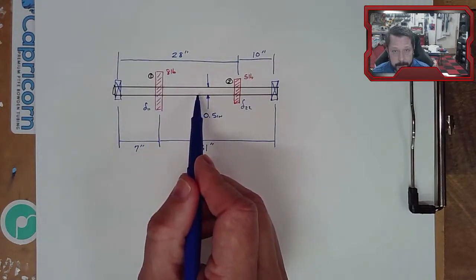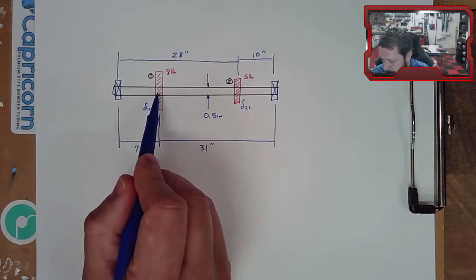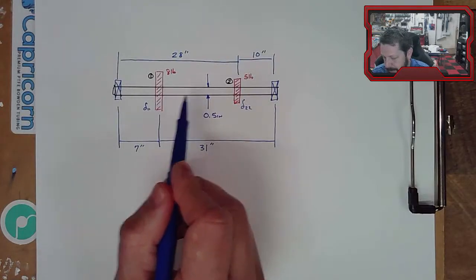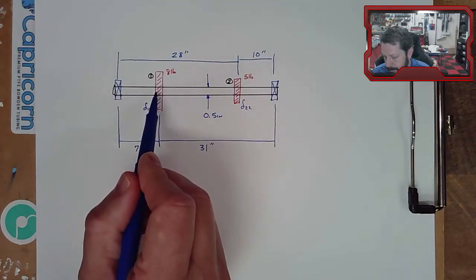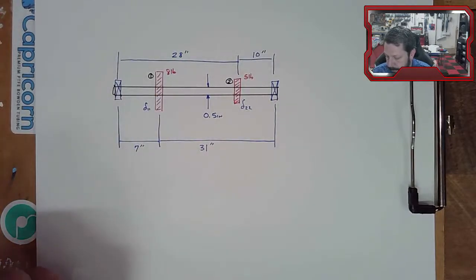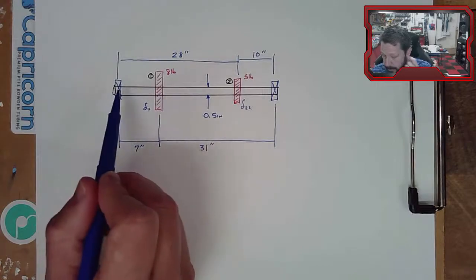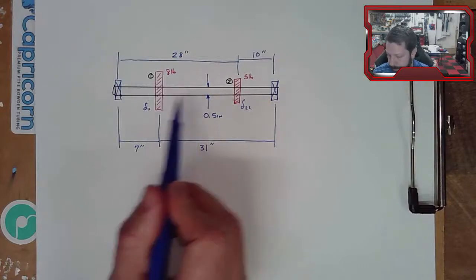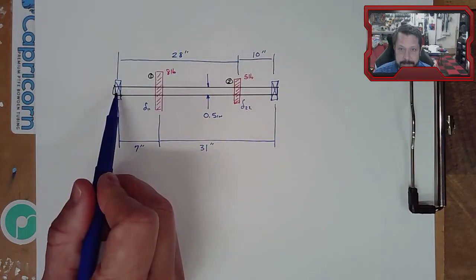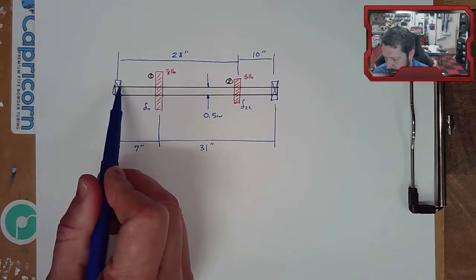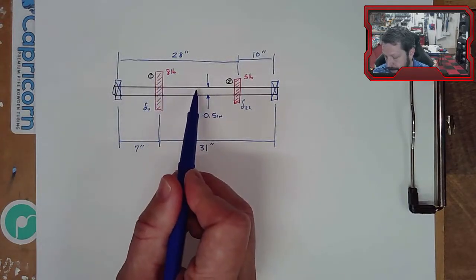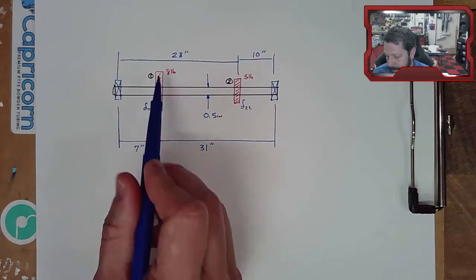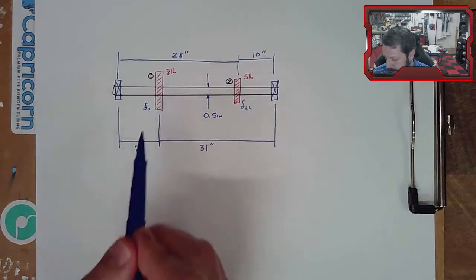It should be a smaller number, right? Since I'm moving 8 pounds to the center, I need a smaller force here to have the same effect at the center that the 8-pound does when it's over towards the edge some. You could think of that. If I move this 8-pound all the way to the end, then it has almost no effect on deflecting the center of the shaft, because it's pretty much all just a shear load at the bearing, more or less. So if I do the opposite, to move this to the center, I need a very light weight here, less than 8 pounds, to have the same effect as this 8-pound gear over here does.